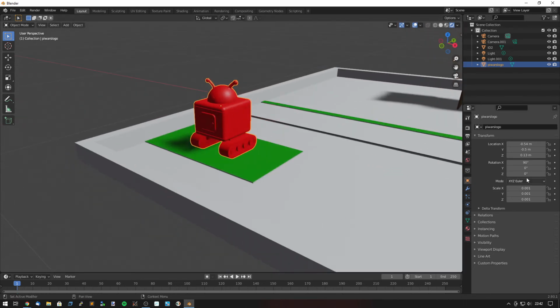But it's facing the wrong way, so I need to rotate it. This time I want to rotate it around the bar that would be going through its Z-axis. So let's click on the Z-axis and rotate it. If you notice, if I go one way, it'll rotate in a negative direction. If I go the other, it'll rotate in a positive. Be a bit careful you don't make sudden mouse movements, because it will suddenly flip around like that.